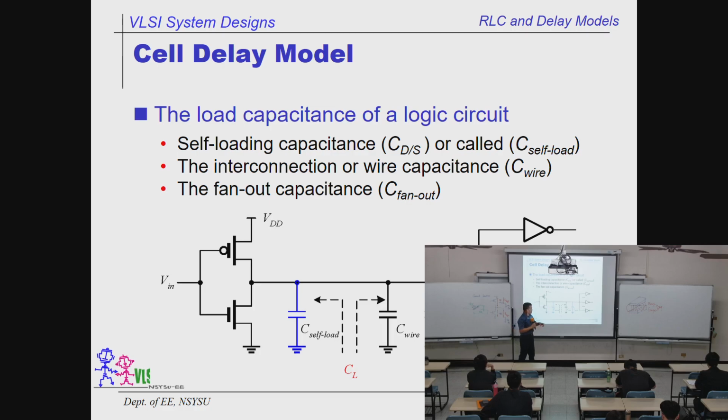The second thing, we understand that according to our introduction, every metal is over the substrate. So the metal and the substrate, there are 2 conductors. So of course they have wire load over there. And since we use a lot of gates, this here is inverters. If you look into the input of the gate, capacitance becomes another load. So we have 1, 2, 3. And the C load usually is a combination of these 2.